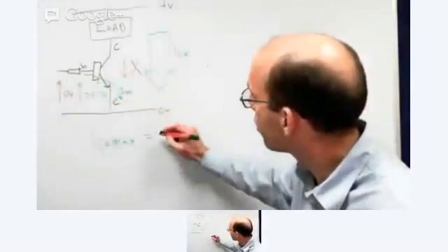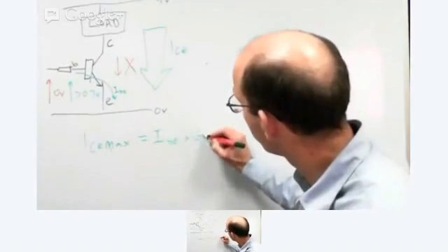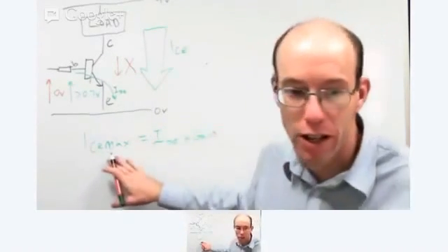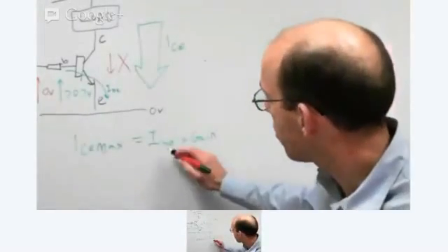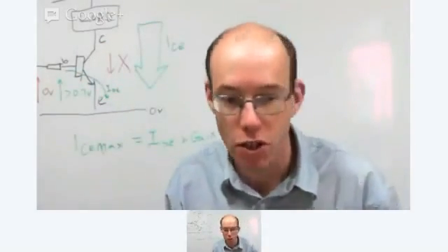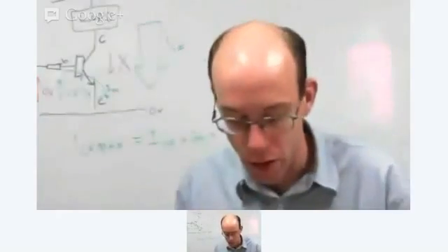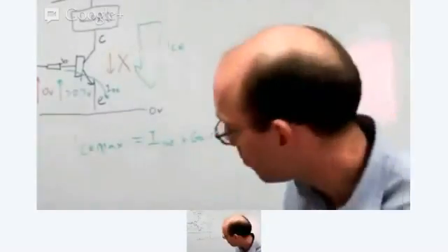So the amount of current that's flowing in through here, IBE, times the gain, gives us the total amount output. A gain might typically be 100 times. So if we're putting in a milliamp in here, we can switch 100 milliamps through the device. So that's just something to be aware of. But most of the time you won't need to worry too much about what the gain of the transistor is.